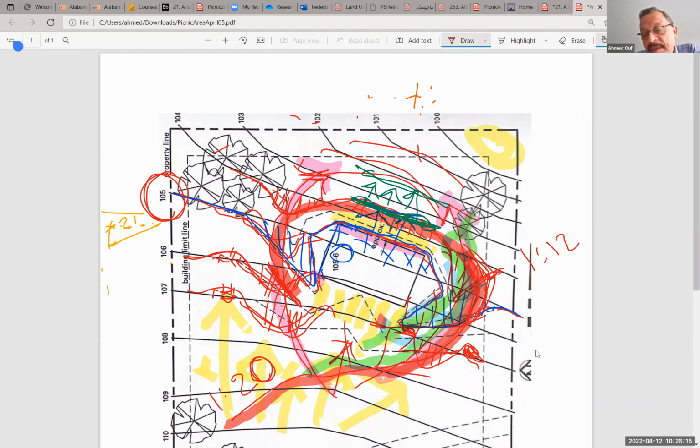And then we need to talk about the back of this building where we are having the pedestrian path go. So how would we deal with the slope here? We need to draw a section or something, whether we need a handrail or would we play with this slope in the back to make it, if it is like 1 to 12 or something, actually acceptable not to have a handrail.